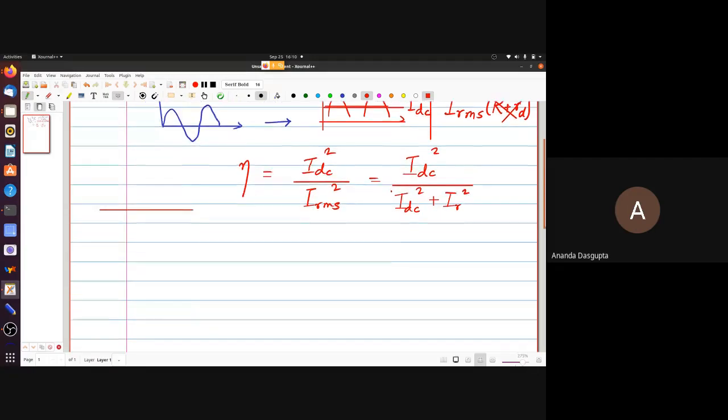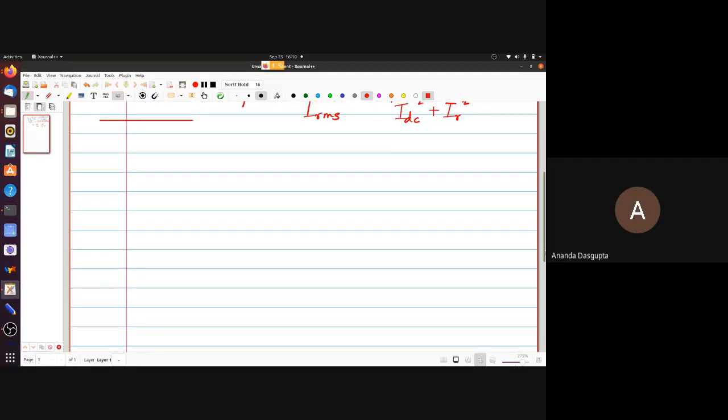It will produce reasonably high voltage, but at low current. And the point is in principle there is no limit, but in practice the limit simply is that you have to be able to ensure that the diodes can hold the huge reverse biases. But you can easily go to a few tens of thousands of volts using this, and you do. This is one of the standard circuits used in small, low energy particle accelerators.